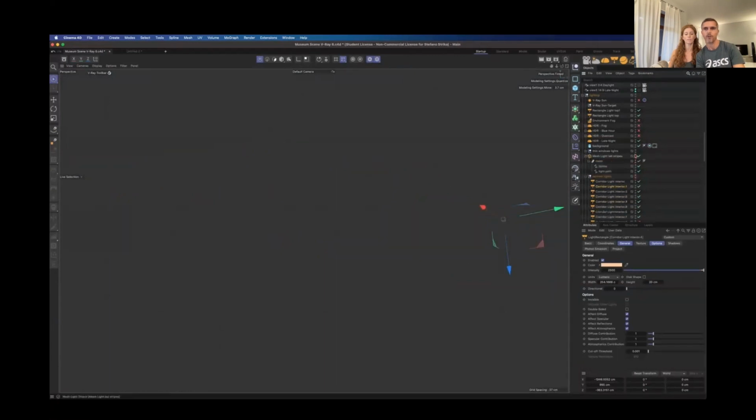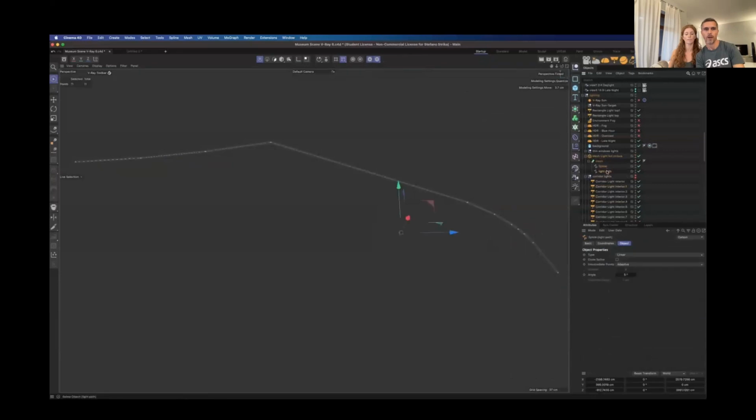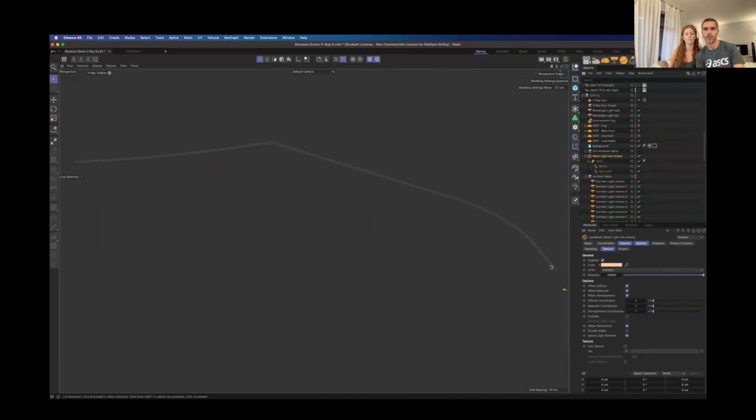Now let's see how we can do that in version 6. We can draw a spline. We can check the length here, about 42 meters. This will help to set the overall intensity. Then use the sweep tool and insert the shape inside the mesh light. Assign the intensity, and we are done.